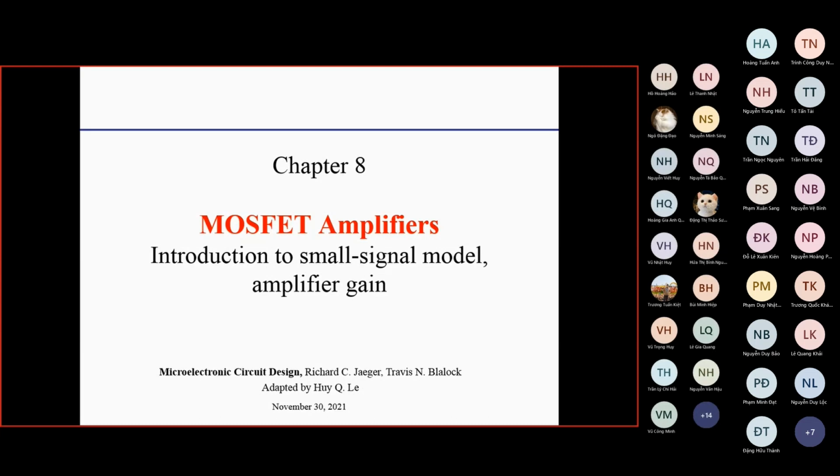For field effect transistor, because the input current IG is equal to 0, we have only two important characteristic curves. The output one, the relationship between the output current ID and the output voltage VDS, and the transfer characteristic curve, the relationship between the output current ID and the input voltage VGS. Okay. So again, these two characteristic curves are very important, right?